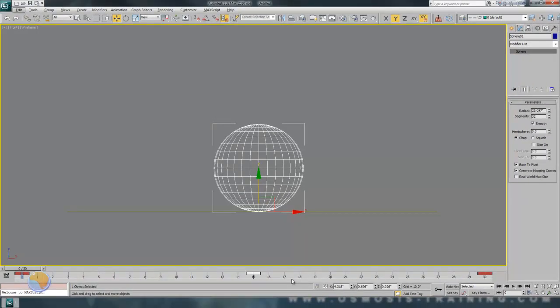Okay, so again, you could do that same thing by holding the Control Alt buttons down and using your right mouse button. This is a real easy way to scale up and down your time bar. And if you wanted to add in negative time, you could Control Alt left mouse button, and that brings in your negative frames. Or if you wanted to scrub or pan your time frames over, you can use Control Alt and your middle mouse button and just pan through those frames.